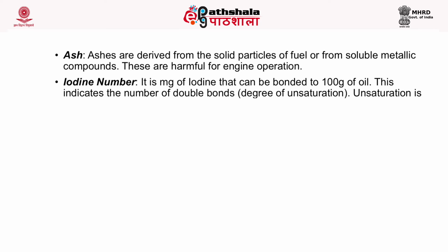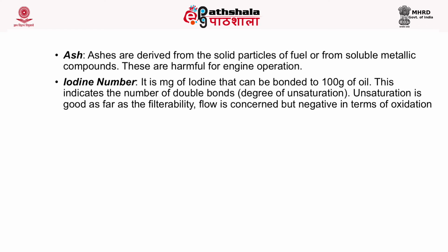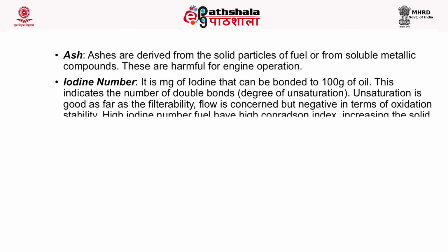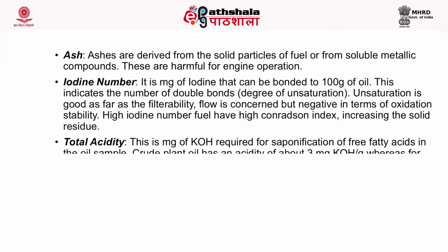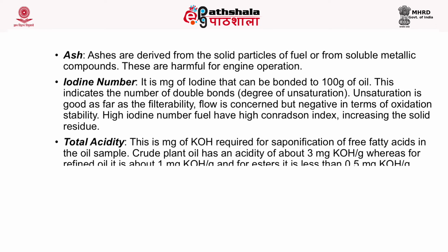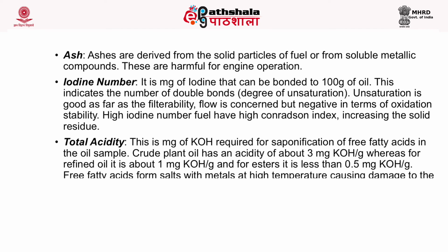Next is the iodine number. It is milligrams of iodine that can be bonded to 100 grams of oil. This indicates the number of double bonds. Unsaturation is good as far as filterability and flow are concerned, but negative in terms of oxidation stability. High iodine number fuel has a high condensation index, increasing the solid residue.